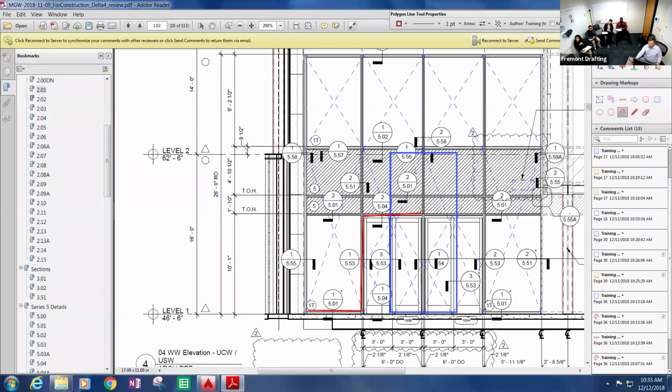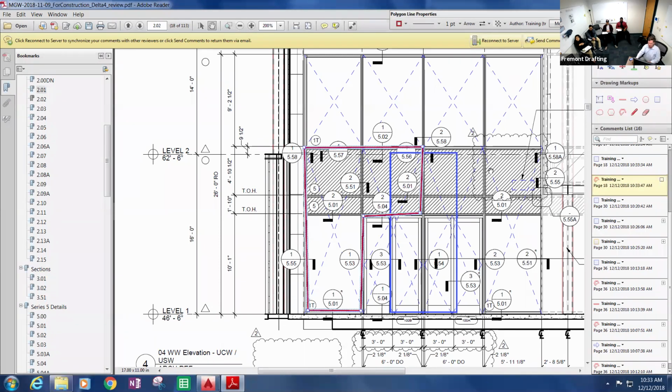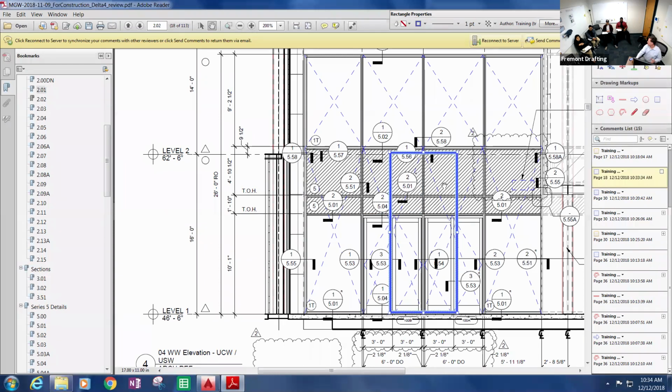Now the tributary area changes just a little bit. It's maybe wider than 5 feet, maybe 5 feet plus half of this other little one, depending on how the doors are made. But generally it's what we've discussed, and there are always going to be some special circumstances here and there that apply.